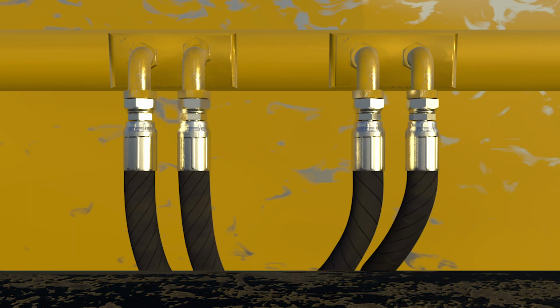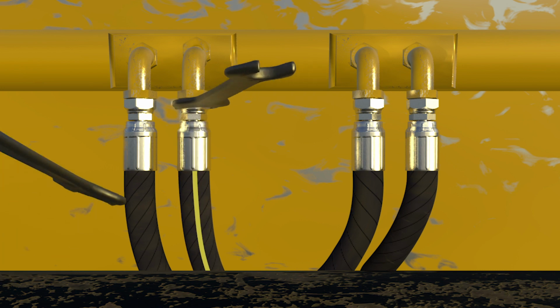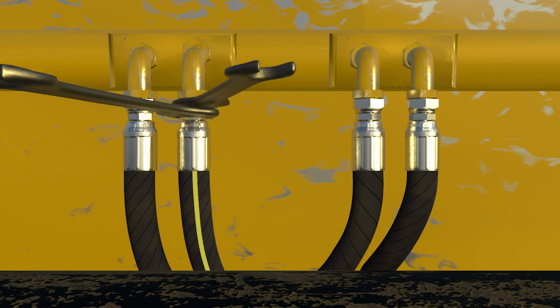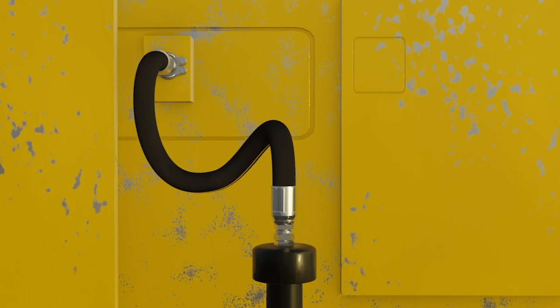In most cases, only one spanner was used to tighten the fitting. As the fitting was being tightened, a twist was applied to the hose. To prevent a twist from occurring, best practice is the use of 2 spanners. One spanner used to tighten the fitting, with the second to counteract the twist. There are many ways in which a twist can be generated by 2 or multi-plane movement.